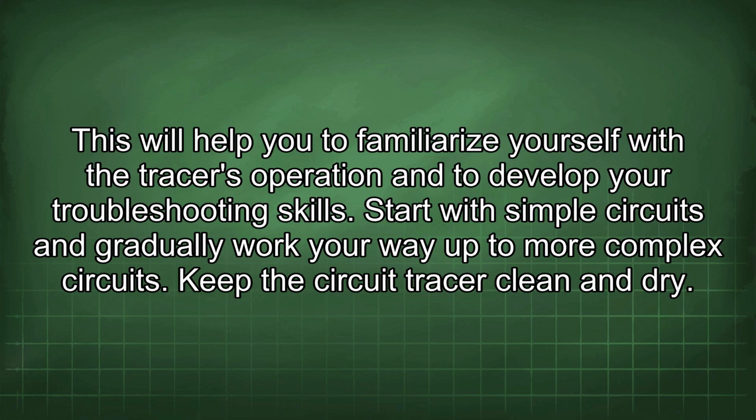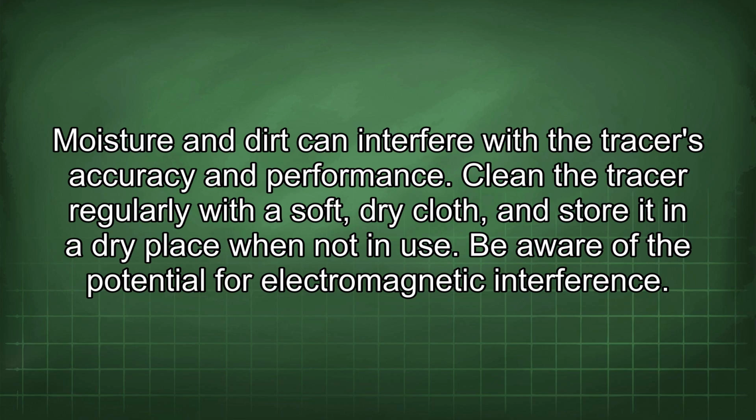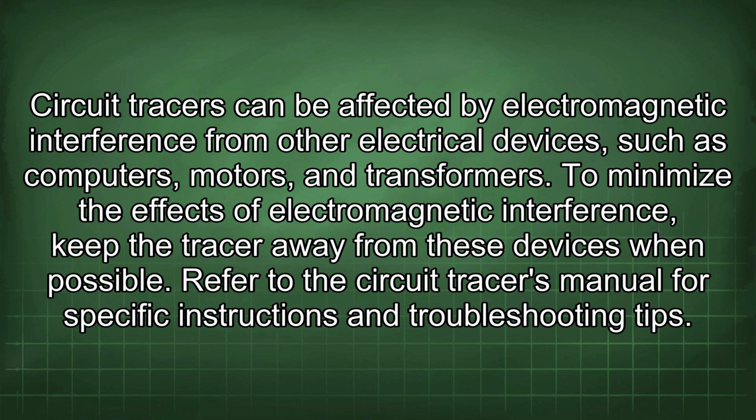Keep the circuit tracer clean and dry. Moisture and dirt can interfere with the tracer's accuracy and performance. Clean the tracer regularly with a soft, dry cloth and store it in a dry place when not in use. Be aware of the potential for electromagnetic interference. Circuit tracers can be affected by electromagnetic interference from other electrical devices, such as computers, motors, and transformers. To minimize the effects of electromagnetic interference, keep the tracer away from these devices when possible.